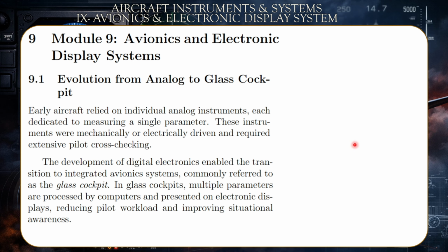Okay, so these are the main premises, the most essential type of data that the pilot needs to be aware of, and they need to be clear and intelligible by the pilot so that he can understand where he is on the map, what is his heading, his altitude, whether he is in a leveled flight or if he's climbing or descending, okay, which is given by the VSI, the altitude again, and the attitude, whether he's in a roll to the right, to the left, or whether he's pitching up and down.